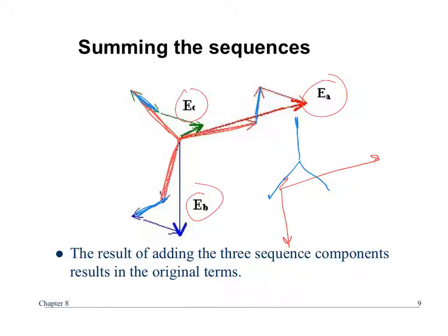Right? They're the same, they're symmetric. And then this one, and this one. Don't they all look like the same magnitude and the same phase? So I rebuilt my asymmetrical ABC into a set of symmetrical components, and they're all balanced.